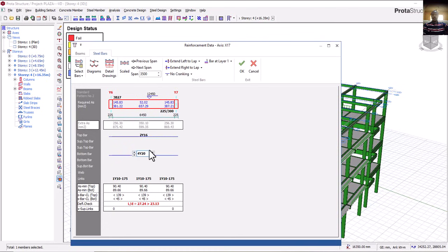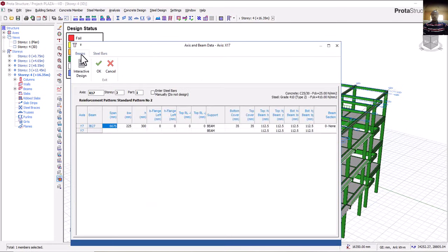Let me see if I increase this. That's why I increased to 4, yet it's still deflecting. So automatically, what will I do? I need to increase the section of this from 300. So I'll come to this place where you're seeing beam and click on that beam.